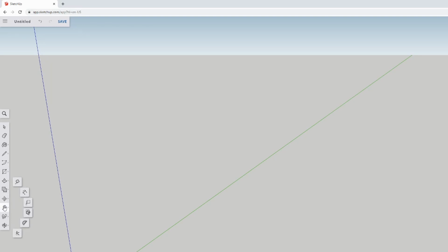The next one is the measuring tool. This one is also a definite go-to. The primary tool that I use is this dimensions button, and I like this because you can select two reference points and it will give you the total distance between those points using whatever scale or system, so metric versus standard or imperial. Tape measure is good too if you want to just identify a pure distance. I don't think it saves to the screen like the dimensioning tool.